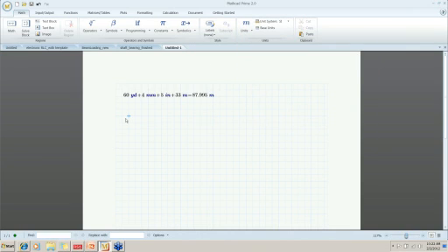As another quick example, if we define mass and set mass equal to 6 kilograms, and then we set acceleration equal to 4 meters per second squared. This is really an example for the benefit of those who aren't familiar with units in Mathcad. If we type mass times acceleration, we get a result of 24 newtons. So the math engine knows what the relationships are. It knows when you multiply kilograms times meters per second squared, you get newtons.